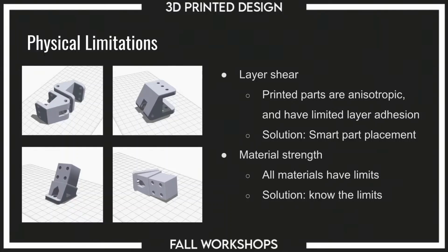During matches and practice, we broke this part a couple times, but then switching to the bottom right-hand corner here, that is no longer a problem because the force being applied in a real situation is going against the grain this time. It's not going with the layers. It's going perpendicular to the layers, so it's less likely to break.